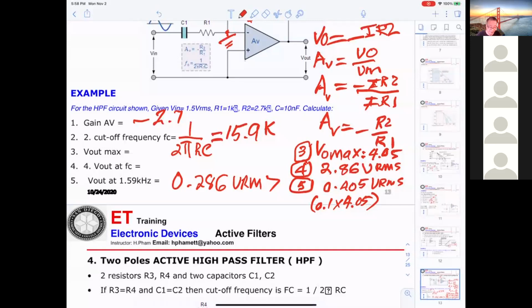You understand, when they say down 20 dB, that means minus 20 dB. You cannot do any calculation with that minus 20 dB. So now you have to find out what number gives minus 20 dB. You take 20 log of 0.1, and that will be minus 20.